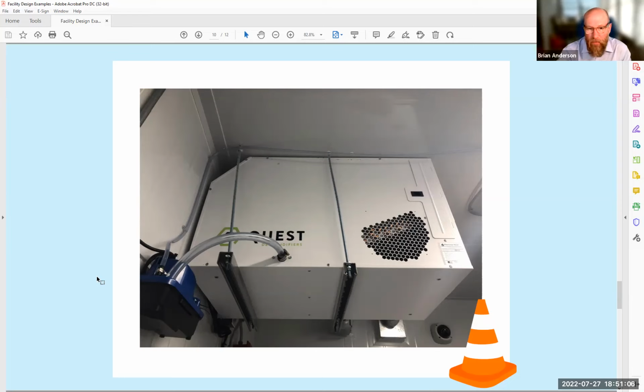So the pipe coming out of the Quest is your condensate pipe. It's going into a little pump. When the float valve reaches an inch, that means there's probably a half an inch of water in the bottom of that sump pump at all times, because it has a float valve, and there's rarely zero tolerance in a float valve. There's typically some tolerance that it has to fill to before it kicks on. It's a little motor. It's got an electric cord coming out of the top of it. That's the black line. And then it pushes it up that other smaller diameter hose and back up and out. Who knows in this facility whether they're collecting that humidification or not.